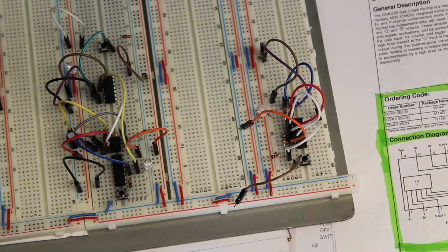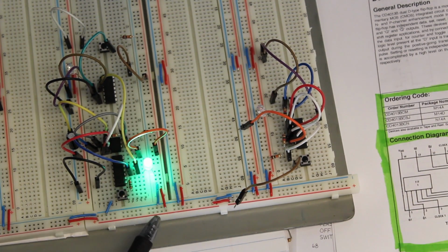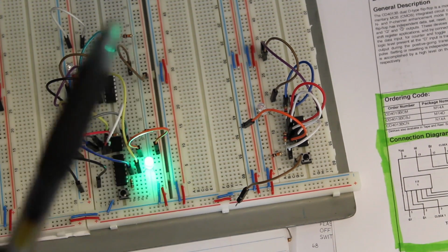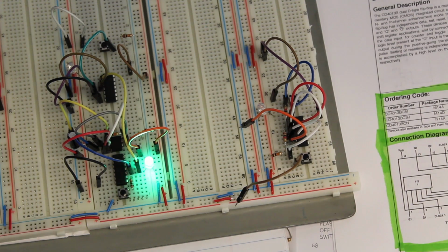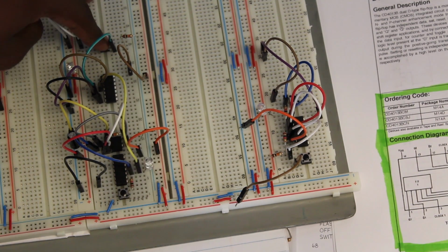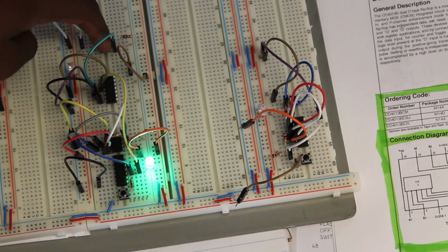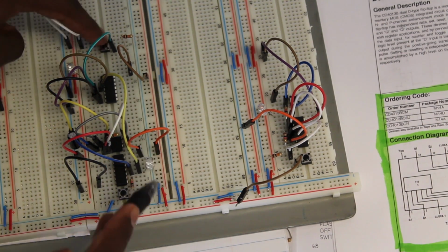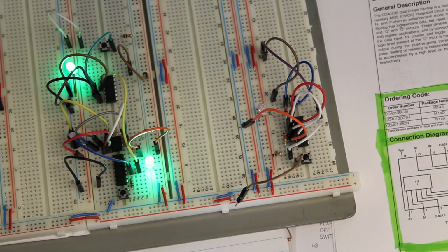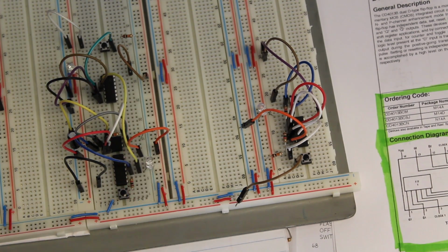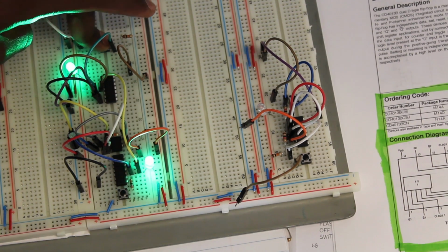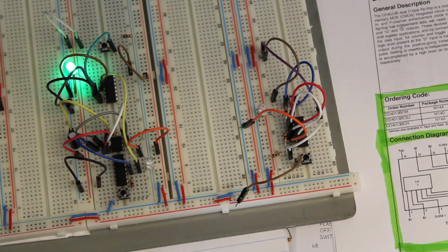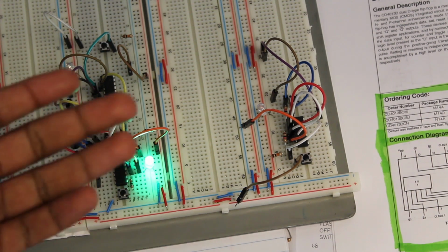Now, back to the flip-flop thing. What we're doing with the flip-flop is we're using the clock to say when we want to set the value. So when I press this button, I'm going to hold it this way. You're going to see something happen. There you go, and it holds it until the next clock cycle comes. I have to hold it until the LED comes up, and then it'll stay on until the next clock cycle comes and resets it.